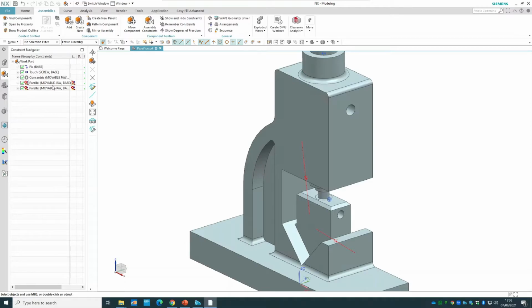And this is the kind of question usually whenever I've been approached by the students, they will panic once they get these errors. So don't worry about it, just double check where you see these errors, and you can easily, for instance, inactivate something. If I untick this one, it will be inactivated, and I can easily find out which of these constraints would interfere. And I can say, okay, if this one interferes, what I can do is easily right click there and click on delete, and then everything seems to be fine and I can continue.